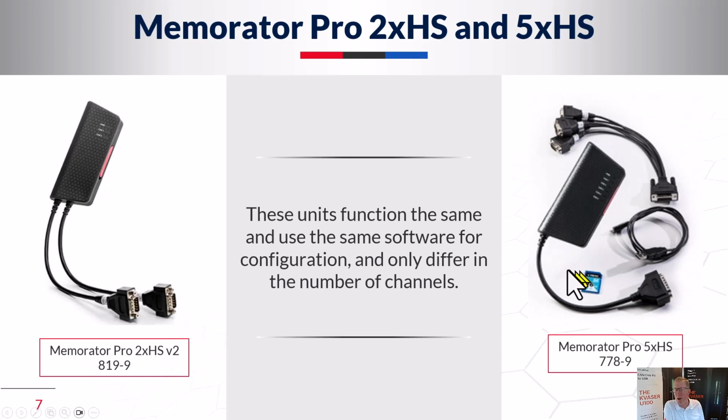They have an SD card for configuration and log data control, as well as script loading and log data storage. This particular one has a pigtail for 5 channels. This one has a direct connection to 2 channels. Again, they both will support the USB. So 2 and 5 channel hardware devices that will act as CAN bus interfaces, as well as data loggers from Kvaser.